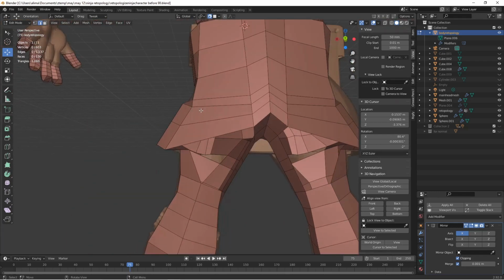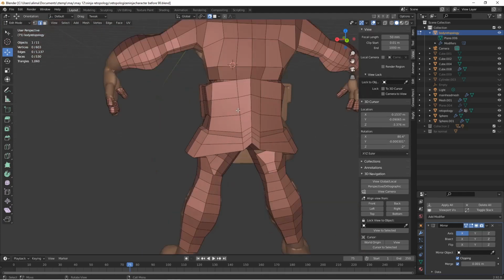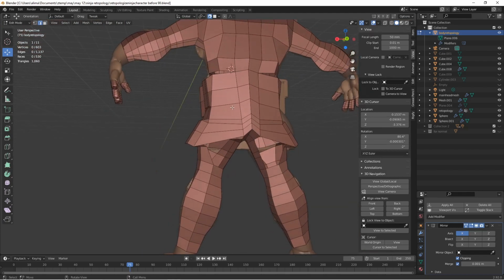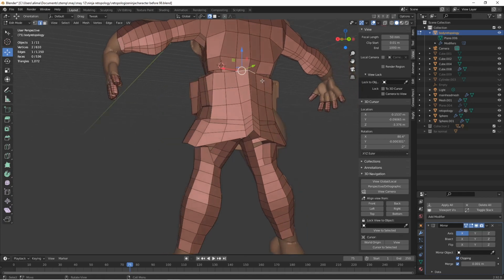Okay, I'm going to hold the middle mouse button, rotate towards the back. I'm going to hold Control, press R, put a loop cut right there. I'm going to select here, right? Pay attention to this. This is connected here. I have my mouse underneath this edge. So when I'm going to separate this, rip this, I'll be connected to this edge because I'm underneath it. It's a small detail, but it's something I think you should know. So if my mouse was above here and I pulled up, the geometry would go up. Because my mouse is beneath here, when I push down, the geometry will pull down, right?